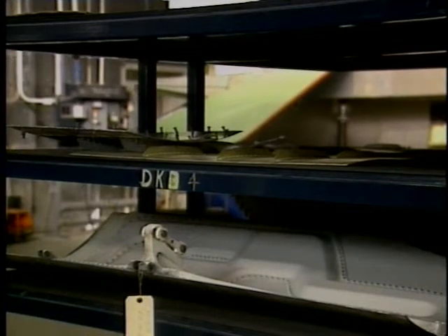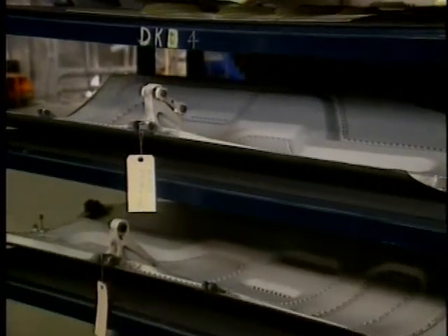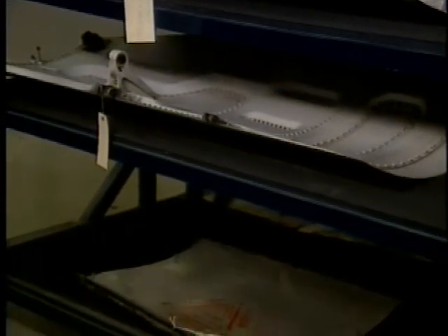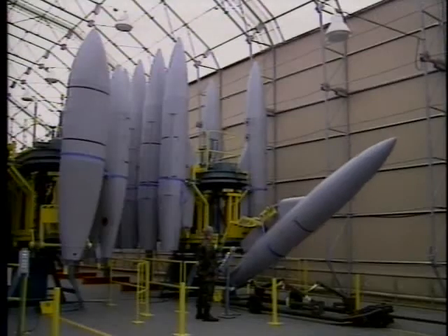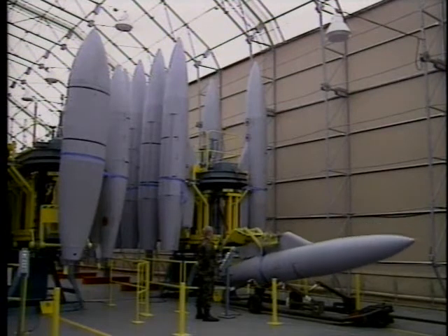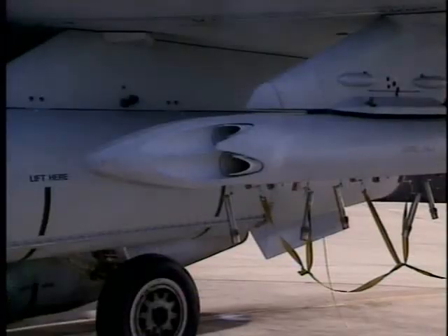Storage racks help prevent unnecessary damage to panels, doors, and other components that are removed during maintenance. If racks aren't available in your work area, ask your supervisor about getting some. Fuel shop, as well as weapons personnel, should be aware of the corrosion associated with external mounted aircraft accessories. Sway braces and other hardware used for attachment purposes are often the center of corrosive environments.